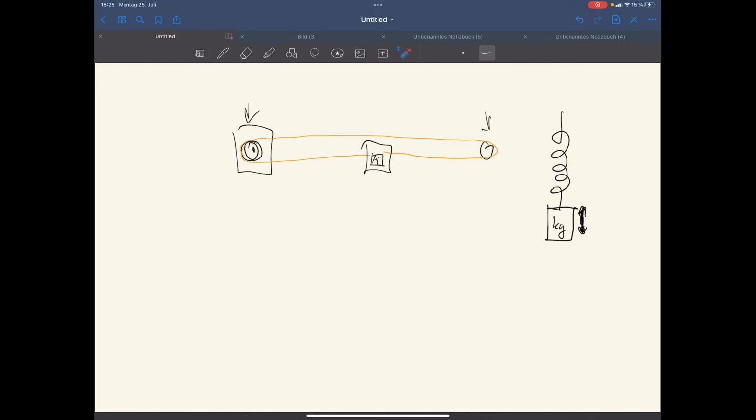So now looking at a perfect printer design, this one here would be perfectly stiff, this one would be perfectly stiff. When we're using aluminum extrusions, those extrusions themselves have a resonance frequency, but this is basically defined by the speed of sound waves within the material, and this is so fast that the resonance frequencies are in a spectrum we don't care about.